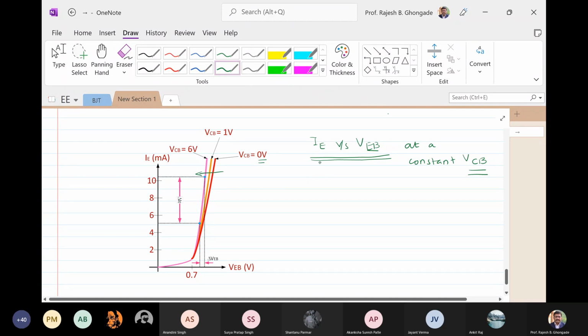बोलो, how do I plot? सर VCB को चेंज करने से कर्व शिफ्ट होता है। VCB अगर मैंने कांस्टेंट रखा एक वैल्यू, समझो VCB मैंने 0 रखा, एंड नाउ इफ आई प्लॉट करना यानी क्या करना है, मैं VEB स्लोली बढ़ाऊंगा और मैं देखूंगा उसका रिकॉर्ड करूंगा IE पे क्या इफेक्ट होता है ना। Yes, I will make VEB, I will change VEB, increase from 0 to some value, and I will note down the value of IE and I will plot it। This exercise I will do for VCB equal to 0।